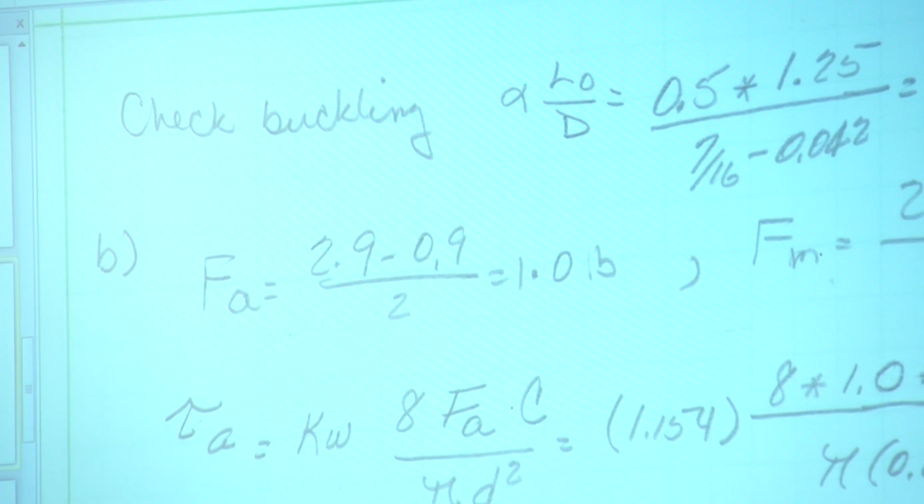In other words, it is very similar to what we did with bolts. There is a preload. However, in the springs, the preload is not as critical as it is in bolts. In springs, it's just to keep it in place so that it doesn't walk away. That's all.